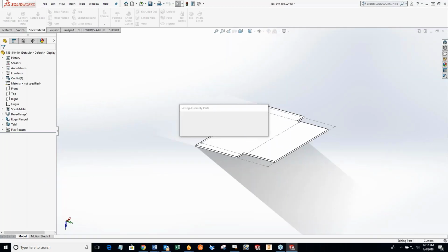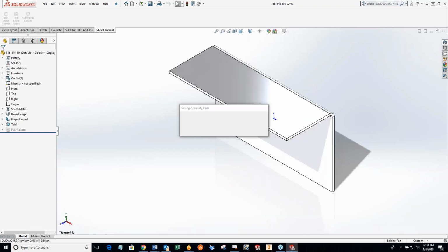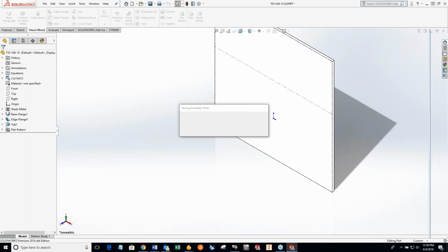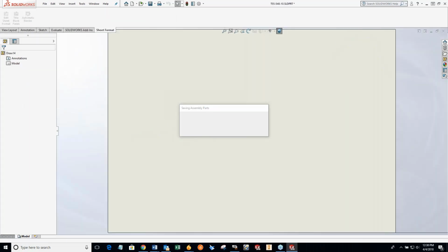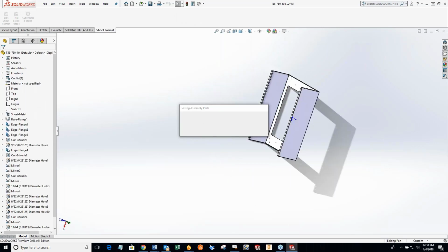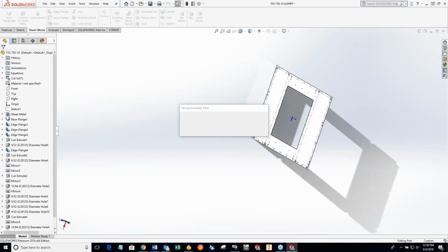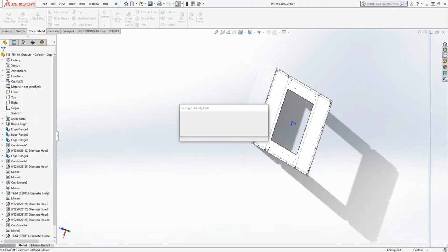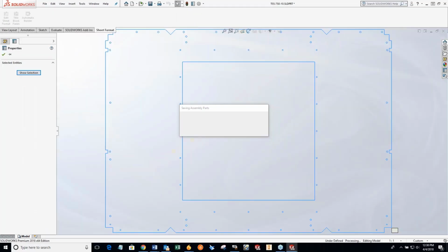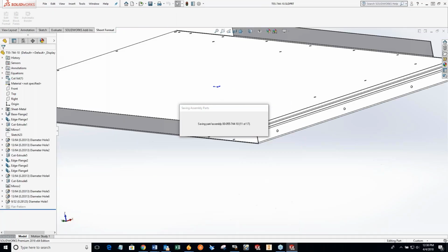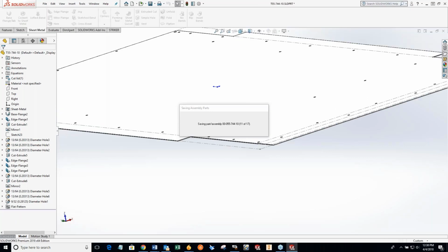And I know Darren and I were actually involved with a company here not too long ago that was using SOLIDWORKS configurations. And configurations we treat very much like assemblies, because I can extract all of the configurations of a SOLIDWORKS part. Well, they had a SOLIDWORKS part that had hundreds of configurations on it, and we let it run through and extract those. We're just calling into SOLIDWORKS, asking SOLIDWORKS to hand us those parts. So it took, I don't remember, 35, 40 minutes, something like that, for it to run through hundreds of parts.